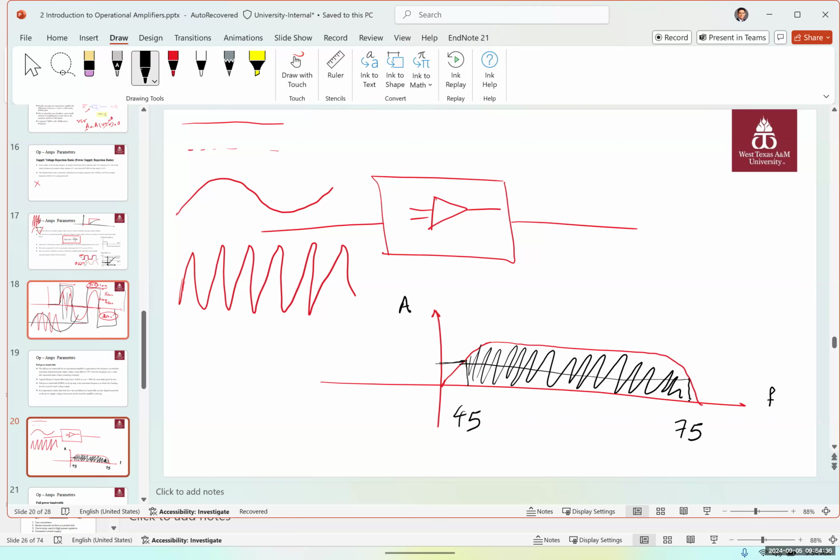So the cutoff frequencies or the limitations in this system are determined by the gain, the voltage gain. And we determine that by using this equation. The cutoff frequency would be square root of 2 over 2 of the maximum gain, or in other words, 0.707. Square root of 2 is 1.41 over 2 is going to 0.707 of maximum gain.